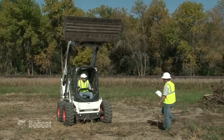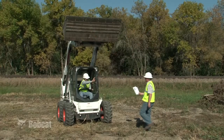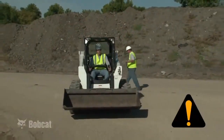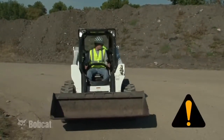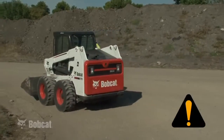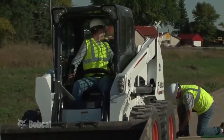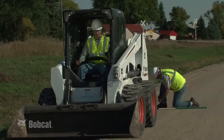Never lift, swing, or move a load over anyone, and never allow anyone to reach under or stand under raised lift arms. Always look in the direction of travel. Look in all directions before moving and look to the rear before backing up. Keep bystanders away from the machine. Failure to maintain a clear view in the direction of travel could result in serious injury or death.